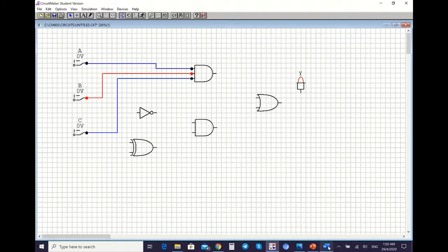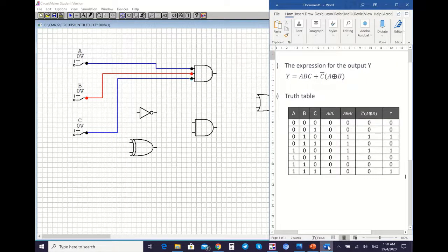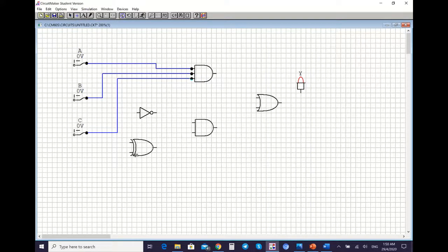Right, so next is the connection for XOR, A XOR with B. This is the first line. Because you already have a line for A, you can take any place here, as long as that's A. For example, I click here and then connect to the first input of the XOR. And the next one is for B.